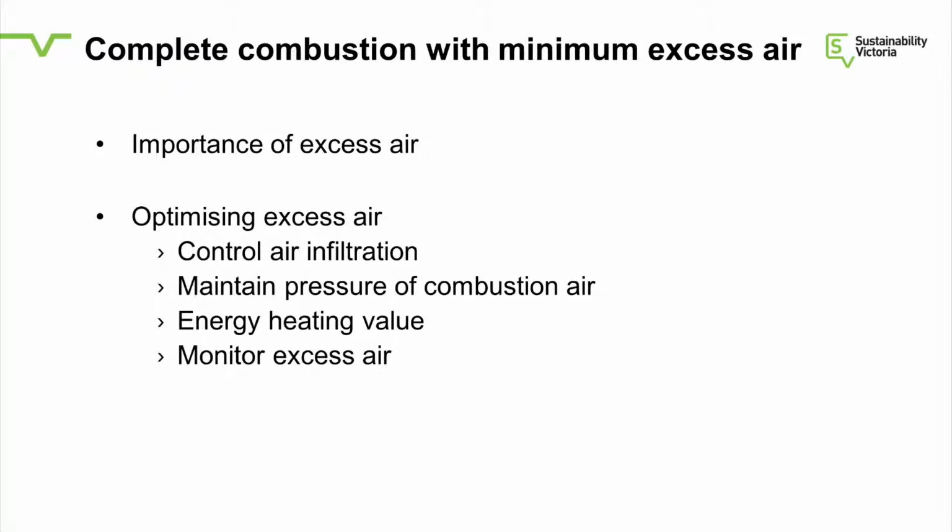Complete combustion, as I said, it's important to minimise the excess air because of the higher temperatures. The game is a lot different here because that air that's being carried out might be being carried out at 800 degrees rather than 200. So that's a large amount of energy lost to the system. And as I say, controlling that excess air, the fuel, monitoring the burner, controlling the burner efficiencies are all fairly critical in keeping the excess air levels down.